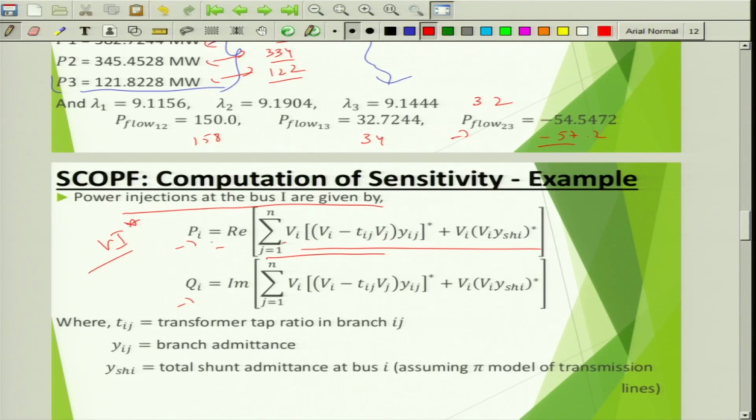So you see here, whatever power flow there is between bus number i and j is considered in this expression, and there is also a local element, there could be local load consumption, and that is being addressed by this expression, Vi into Vi, that means basically V square by R, otherwise you can say V square into admittance, shunt admittance, that is it. So that is the self power flow, the local power flow.